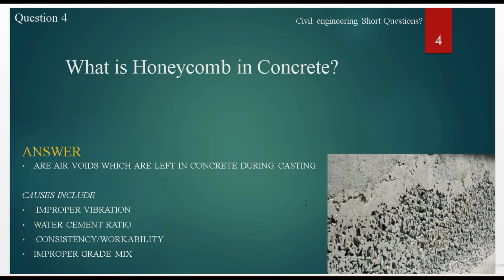So when the concrete is casted, during that phase, when too much water is added into it, or when it's not vibrated thoroughly, and when there's a problem with its consistency or workability, and when there's a problem with the grade mix of the batch. But basically, honeycombs are the left air voids, which happen during the batching or pouring or casting of concrete, and they're very common on sites.